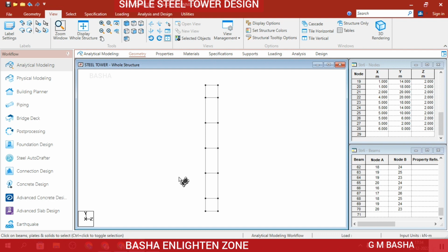If I give cross bracing, again it will take some extra time to assign properties to those particular bracings. Okay. If the width is more than some 5 meters or 3 meters, then at that time you have to give the cross members also. But I will choose 2 meters only here. Then in the right view you can see the same frame appears here.